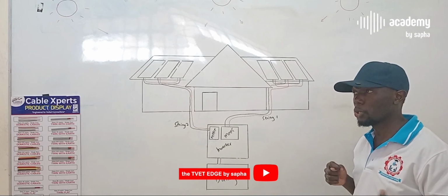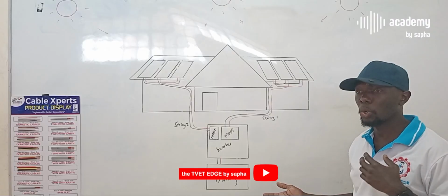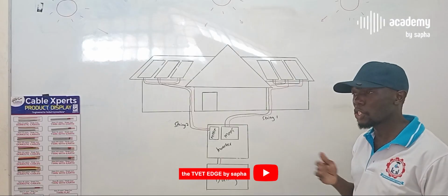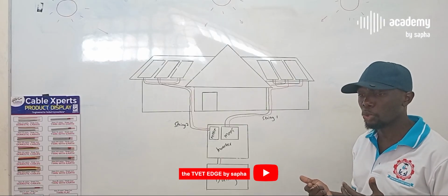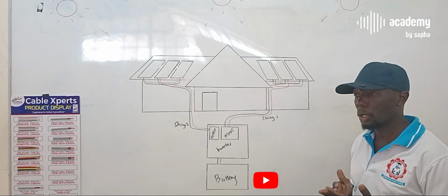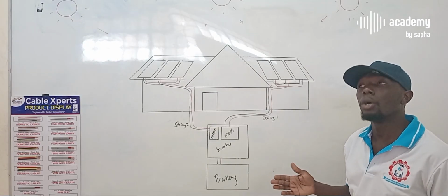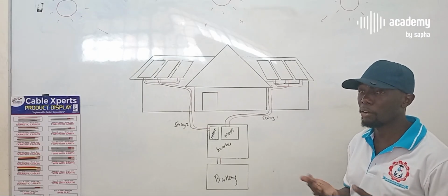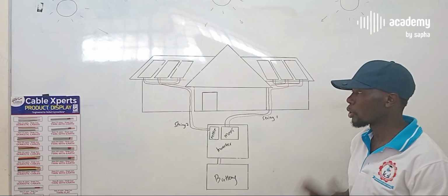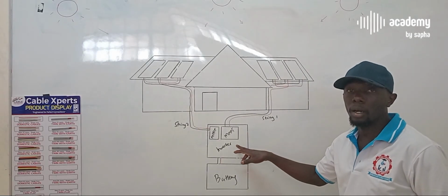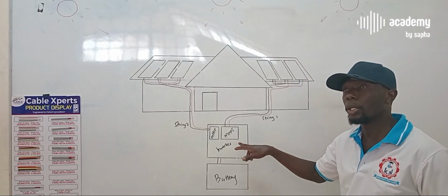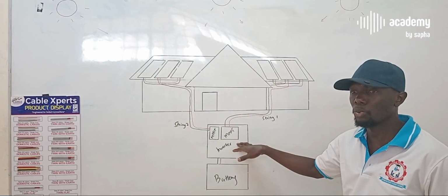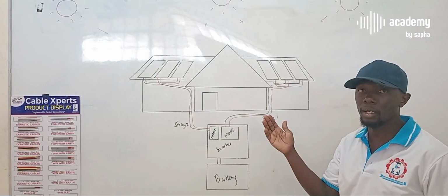We've learned about the different configurations of panel connections. You can have a series connection, a parallel connection, or a combination of both series and parallel. This is to ensure that the intended output is achieved within the time period. For example, if you intend to generate X amount of power within 6 hours, you can combine series and parallel to also meet the inverter input parameters, because some inverters will only start working at X volts.